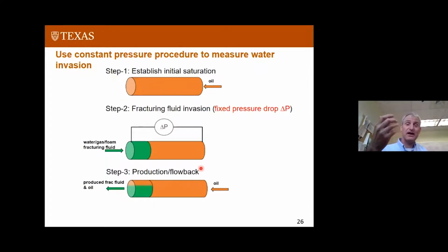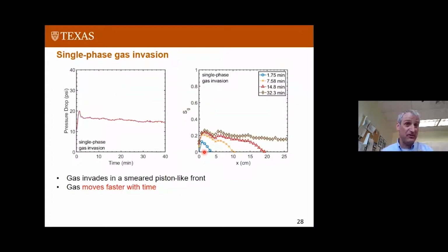Going back to our picture to begin with, this fracture is going into the whole reservoir, and this invasion step isn't basically something coming out the other end. The invasion is all pressure driven. Okay, this is basically locked up on the other end, and the other end isn't centimeters away like it is in our lab. The other end is hundreds of meters away or tens of meters away. So invasion still needs to be understood a little bit better here, because the lab doesn't mimic it as well as the production step.